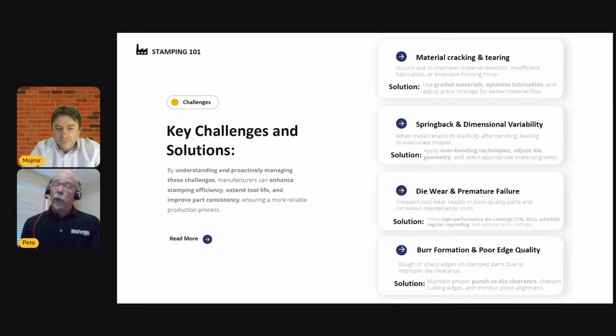So where it might seem like I start running and now my material's not working, it might not be a material problem. And on the other hand, as we start to build more heat, our lubricants can break down. So where it may appear again that the material is failing when we're running faster or we're generating more heat, it could be a lubrication issue. So what you're beginning to see here is metal stamping is a highly interactive process. Everything affects everything else. It's not one thing standing on its own. That's why solving metal forming problems can be very challenging.